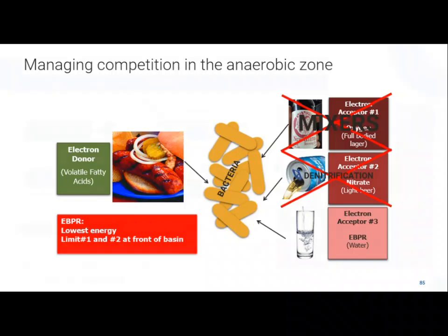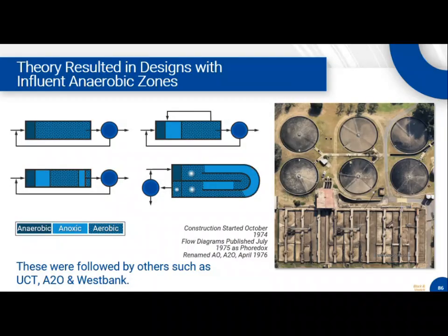And that's why you see differences in complexity in BNR configurations. So when we just do some kind of this theory, we get a lot of different ways to put in biological nutrient removal in activated sludge plants. Like this one, there's an anaerobic condition at the front end of the basin, and then it's just aerobic. And they get biological phosphorus removal. What plant does this remind anyone of? Cruise, right? Probably Mountain Creek too.